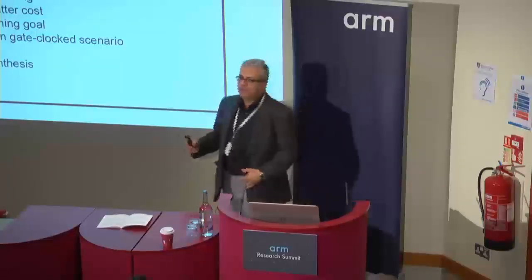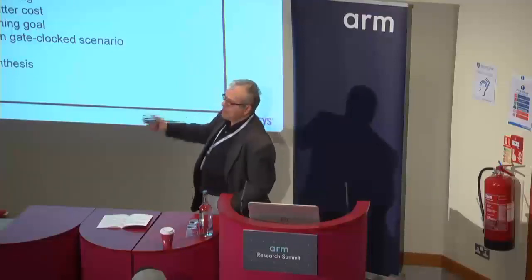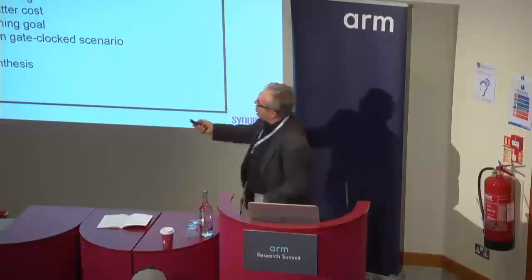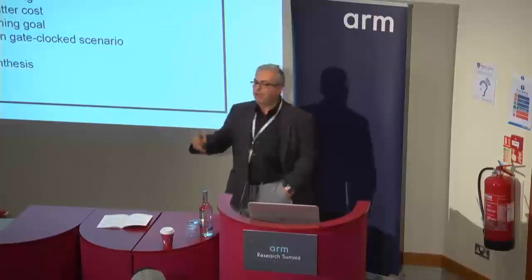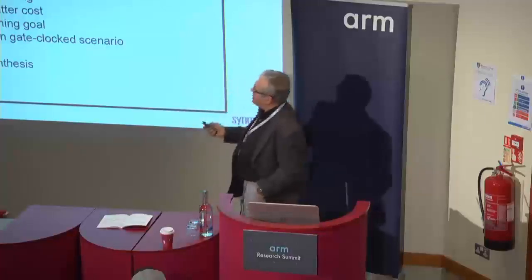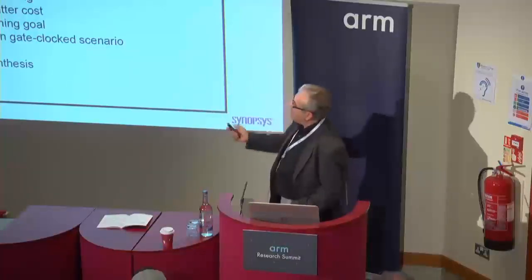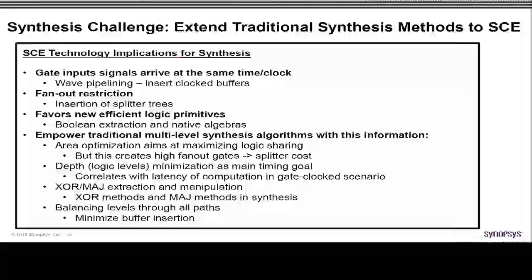And it's all costly. That gives special challenges for synthesis, including insertion of splitters, including what do you want to do after you do the synthesis. How do you deal with place and route? And I'll be talking about that in a second. But essentially, the synthesis has pretty tough challenges related to path balancing and related to clocking strategy. And different families have different optimization techniques.